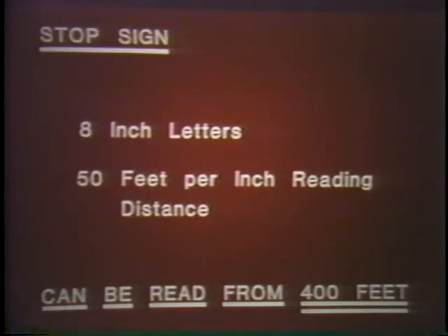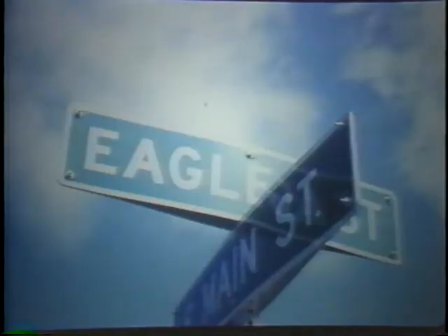Part 6 of the MUTCD contains detailed instructions on signing and traffic control in work and incident management zones. Warning signs and guide signs should be black on orange when they're used in temporary situations. The size of the sign and the size of the letters are very important because the time it takes drivers to react to a sign is directly related to their ability to detect and read the sign in time to react. Drivers in unfamiliar areas at night find minimum-sized street name signs to be a big problem.